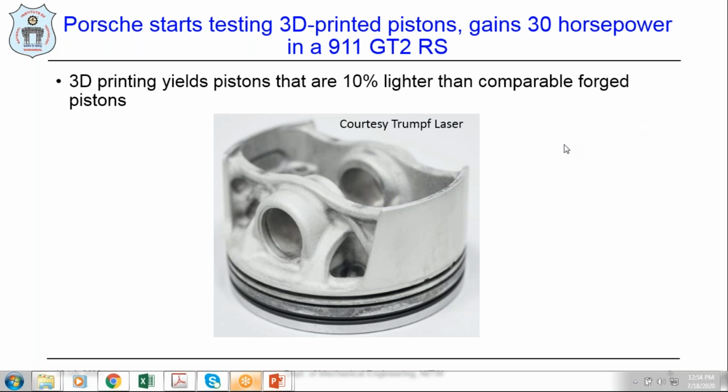Also, we have heard about the leading edge aviation propulsion fuel nozzle in an Airbus or a Boeing, manufactured by GE suppliers. It is already implemented and widely used in the industry. Why are we using these additive manufactured components? It increases the efficiency of the engine, reduces fuel consumption, and can withstand high temperatures from 800 to more than 1500 degrees.